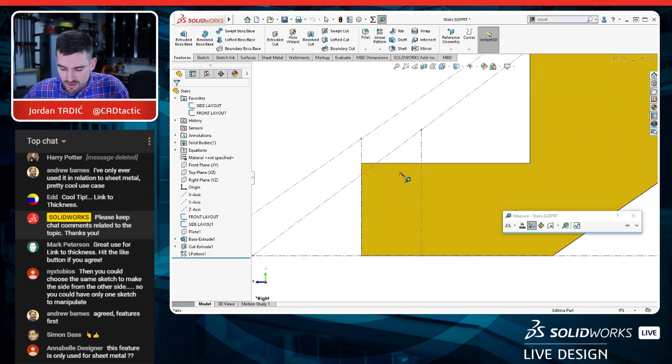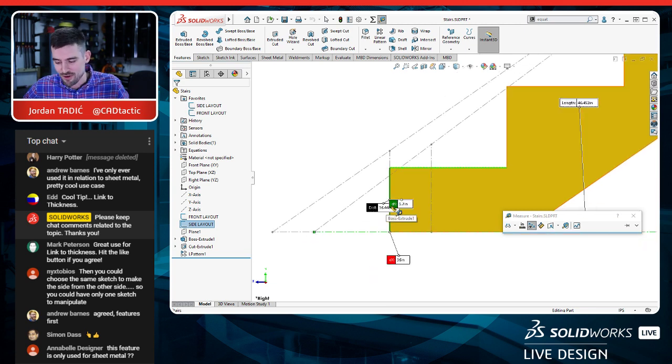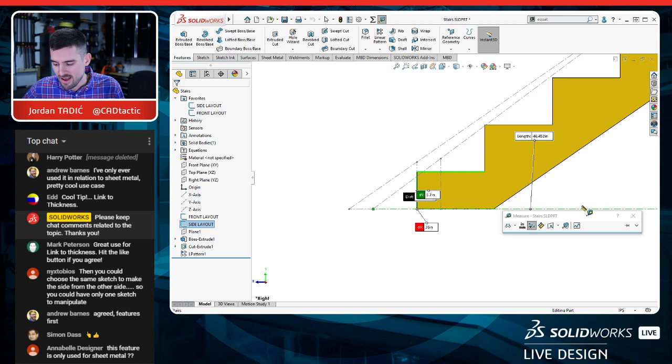What about this distance right here, from this to the ground? 5.7. Well, remember, we're going to have a tread plate up on top of that, which is 1.5 inches thick. So 5.7 plus 1.5 is 7.2. Perfect. And then let's clear these selections.